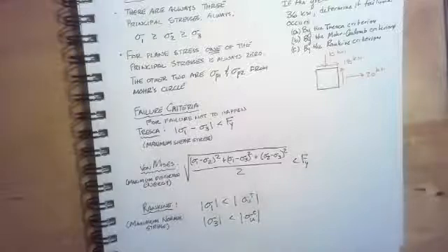So as we have Tresca and von Mises, we have two formulas here that we would use with ductile materials. Tresca is more strict. However, von Mises has to do more with distortion energy. So a lot of individuals would use the von Mises criterion. You would want to check with whatever codes or design standards you're working with as to what you would want to apply for your particular application, or use good engineering judgment with whatever problem you're working with.